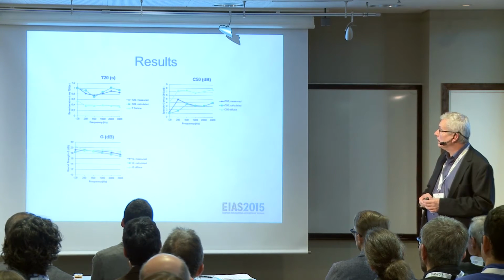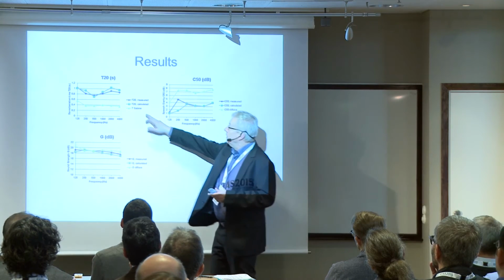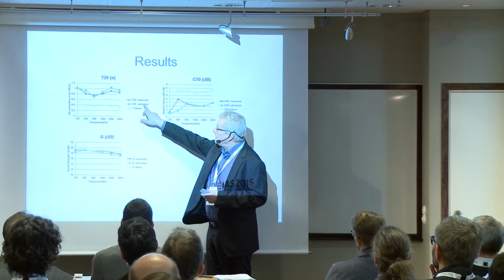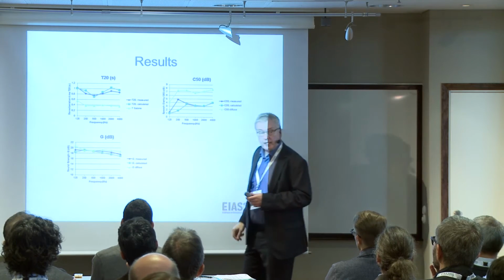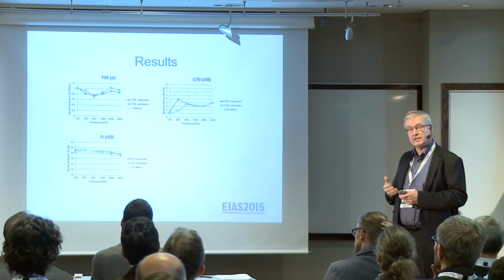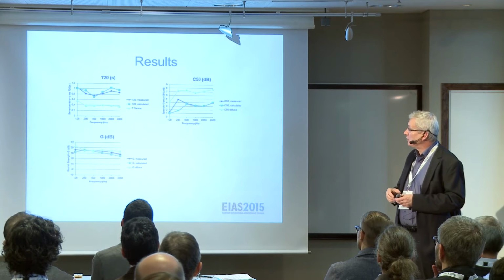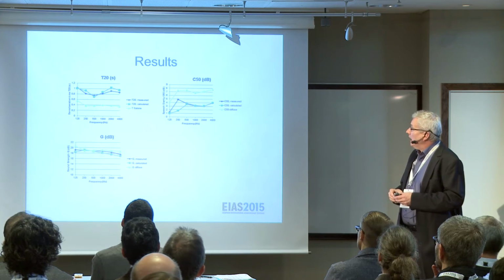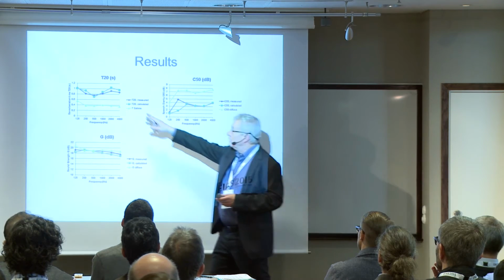So if we look at the results, it looks like this. If we look at the reverberation time, the blue one is measured, the green one is calculated, and the yellow one here is the Sabine. And you can see there's quite a large difference between what we measure and what we calculate by the Sabine equation. It really doesn't work in this type of room. But you can see it's quite a good correspondence.